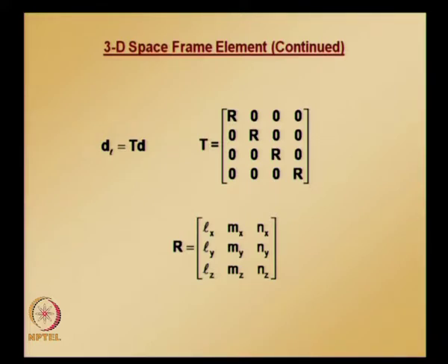That is the angle by which the element needs to be rotated about the local x axis such that the local y axis is parallel to the global y axis. We require that in addition to the coordinates of the endpoints of the space frame element. So this is the data required for the orientation angle method.